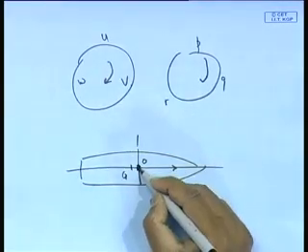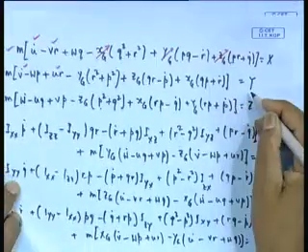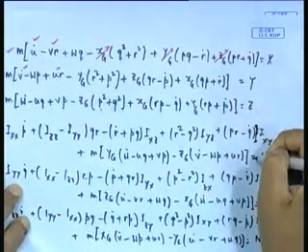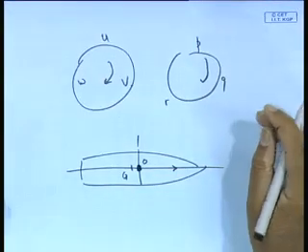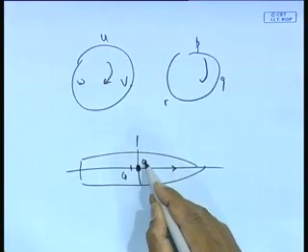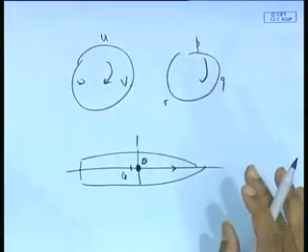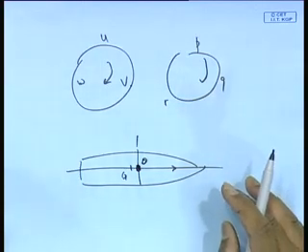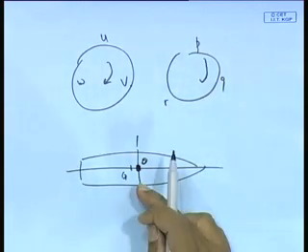Why? Because remember, I have to measure the forces at some point of time, all these x, y, z forces. Quite often it may be convenient to define the forces with respect to a point which is fixed on the geometry, not on the center of gravity. Remember, if I take a point O, which is somewhere like say LBP midship, that is a geometrically fixed point, but the center of gravity point depends on the kind of loading. Suppose I take a particular hull, I would have midship at a given location, but its LCG can be anywhere depending on the loading condition.